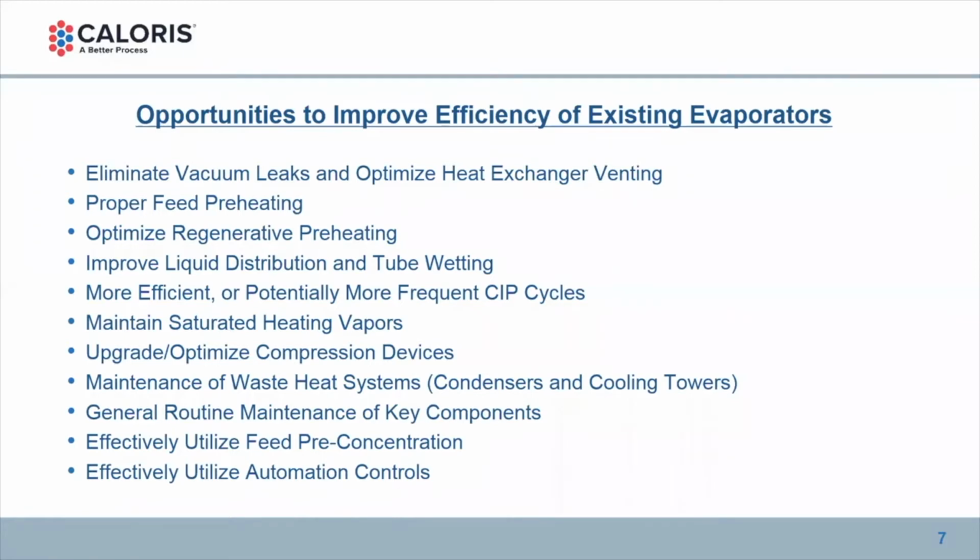Maintaining saturated heating vapors, optimizing, possibly modifying the compression devices, be it the turbofan or TVRs, the waste heat systems, condensers and cooling towers, general routine maintenance, feed preconcentration, and automation. All actions and steps that we've utilized to improve the efficiency of somebody's evaporator over the years.